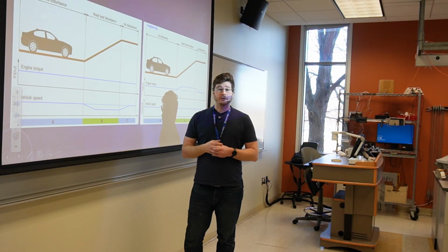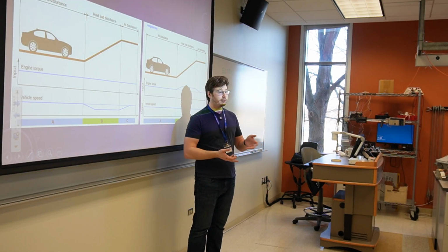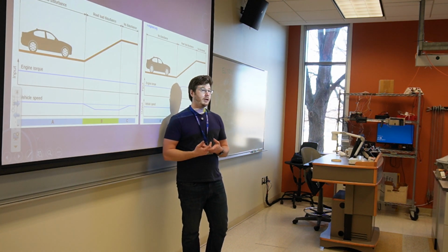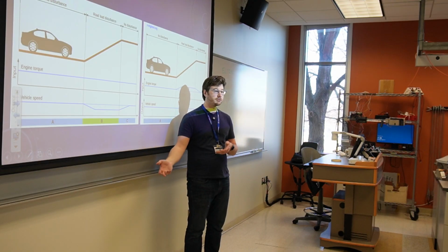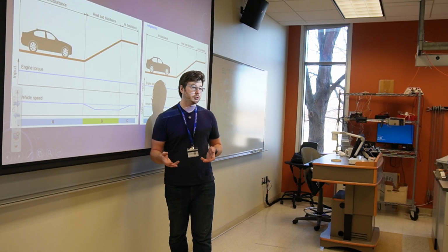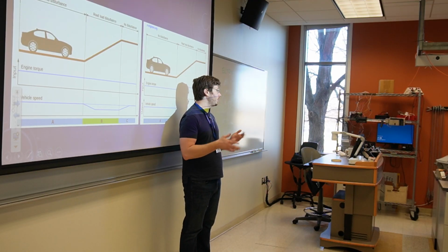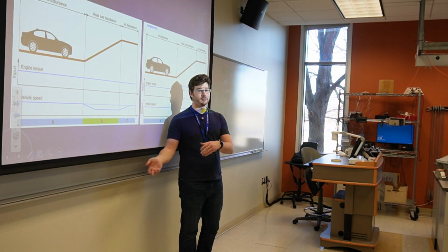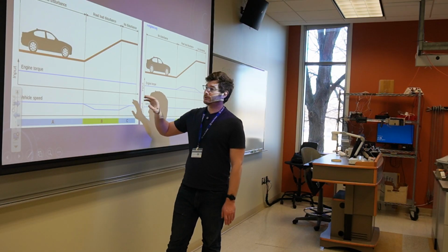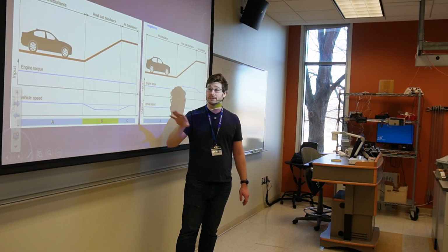Motor speed, for example, if we know that we apply 50% of the voltage, if we have a 12 volt system, we apply 6 volts, we know it'll go a certain speed. If we apply the full 12 volts, it'll go twice that speed, for example, or half, depending on how you look at it, right? So that's an open loop control, where we command the motor, but we don't really know how fast we're going. We kind of know how fast, 10%, 100%. And we have an idea that generally in a situation when we apply 80% of our power, we'll go this fast. Okay, that's an open loop system.